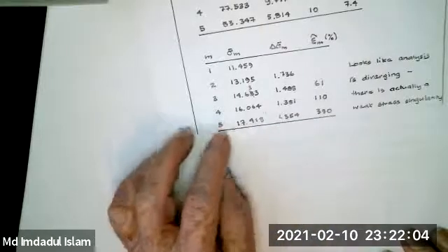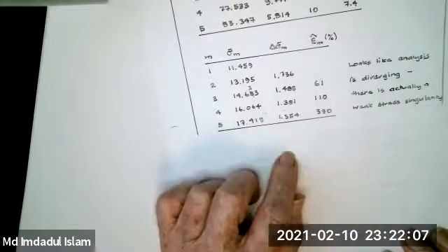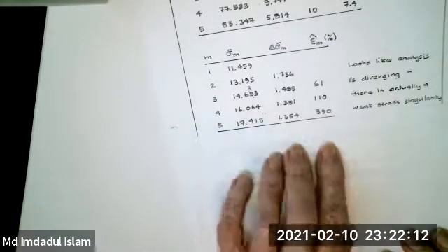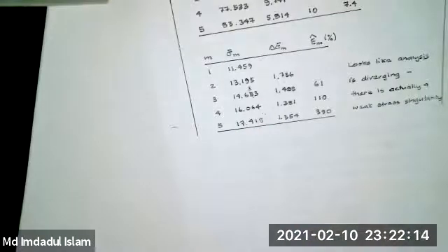What happens eventually, if you keep refining this mesh, this thing will start to diverge. This thing will start to increase, reflecting the stress singularity. But what can happen here is you can get an error estimate on a singular problem using the estimate I've given you. Fine, but it'll always be unacceptable. At least in our experience, it'll always be unacceptable. And there's some underlying reason for that. It's because the divergence of the singular part of the stress has not yet overwhelmed the regular part, but nonetheless, it's screwing it up and making the convergence rate extremely slow.